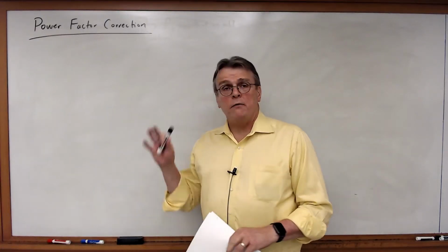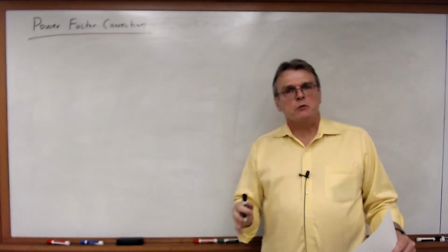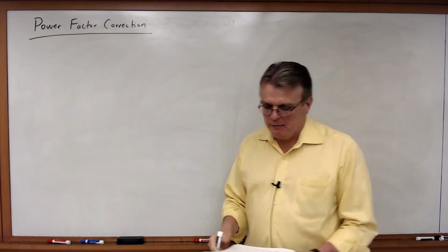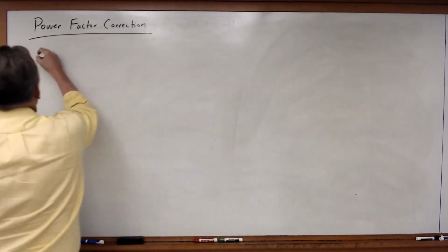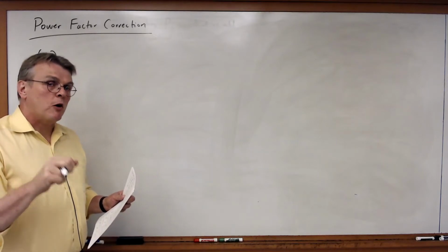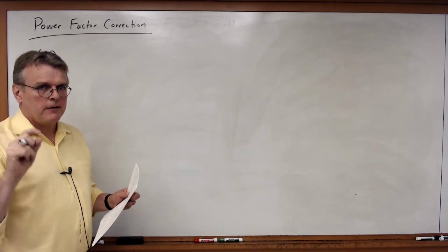Okay, let's look at a few more points concerning power factor correction, and let's do a couple more examples to show how the technique works. So first of all, just a few things to keep in mind. First of all, a power factor correction capacitor should always be connected in parallel across an inductive load, not in series.